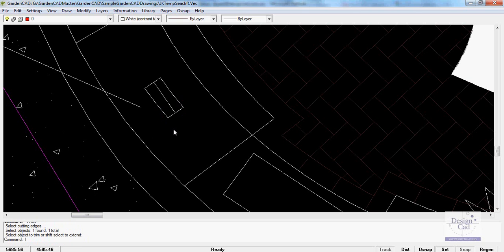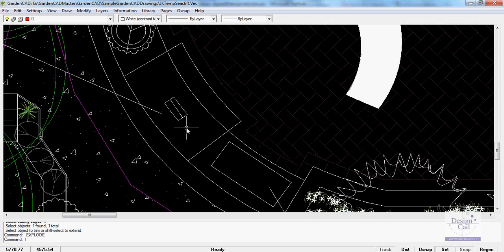So we've drawn a line through the center of that rectangle. Sometimes with other entities you have to explode. If you've got a complex entity, you may not be able to trim, and you may have to explode it. So you might pick on a rectangle. If your trim's not working, pick on the rectangle, right click, and explode it. Now you've got 4 separate lines, in fact more than that in this particular instance, and we've got a couple of lines through here, but we've got the chimney in place. Let's remove that line because that was a dummy line. So there's the chimney through there.